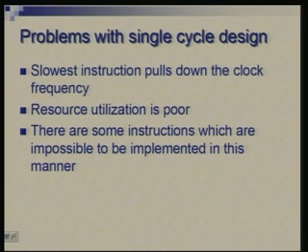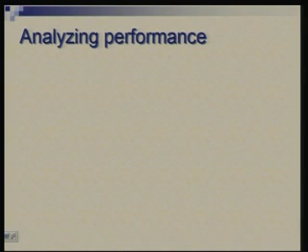And secondly, resource utilization is poor. Apart from having a full fledged ALU, we had to use two adders, and we had to keep the instruction memory and data memory separate, because in that type of design it is not possible to work with a single memory from where you fetch an instruction and then later on fetch data also. So, that will not work out. Also, I hinted at some kinds of instructions which cannot be realized by this type of approach. So, we will focus today on the first two issues.